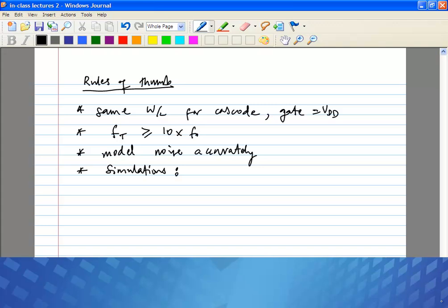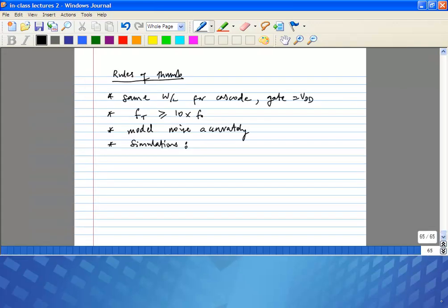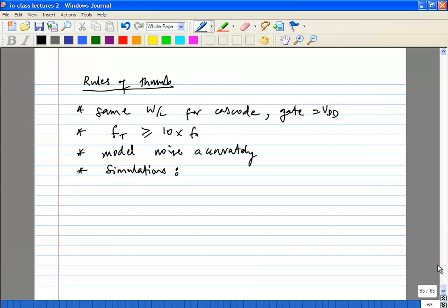So a good thing to plot is, most of our hand calculations are for square law devices, right? So, okay, plot Ft, Gm and gamma as a function of I bias and width. What does this give you?